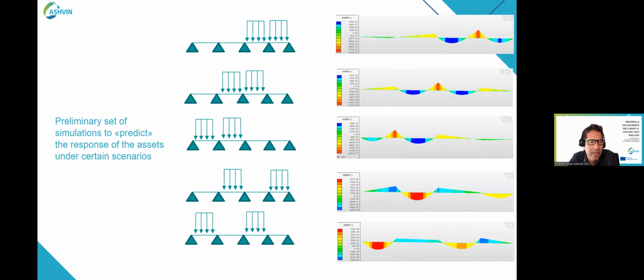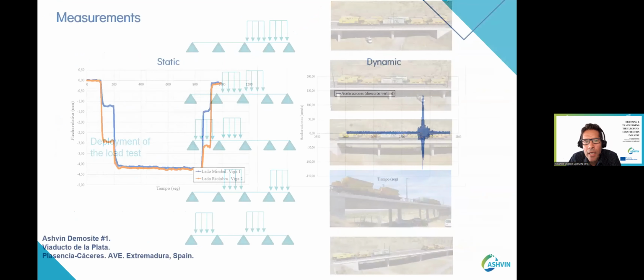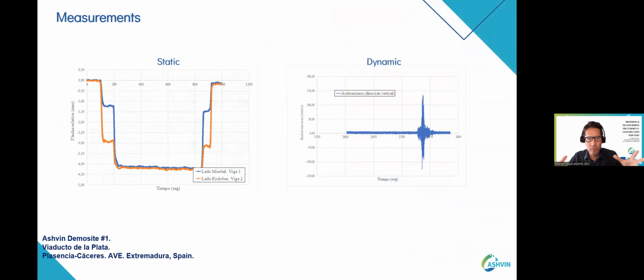So here we can see, let's say, the preliminary sets of simulations that are quite standard from the structural perspective under certain scenarios. Here we have the scenarios with the locomotives applied as loads, with the abstract representation of those beams, as structural engineers do. We measured together with collaborators, or we collaborated in those measurements, both the static measurements and the dynamic measurements, which are routine as well.